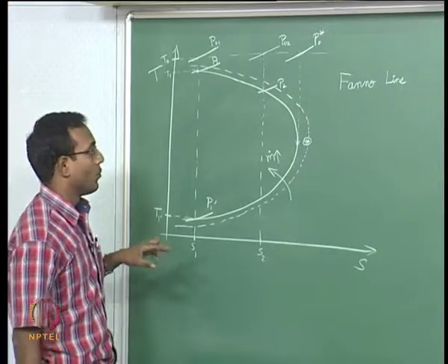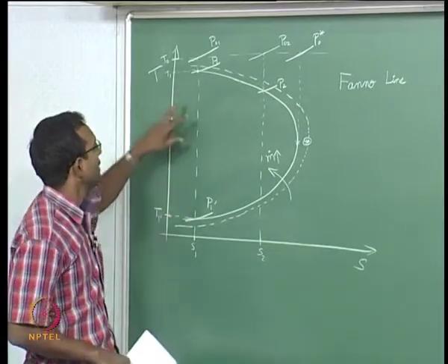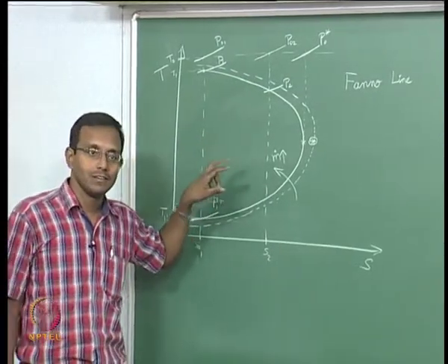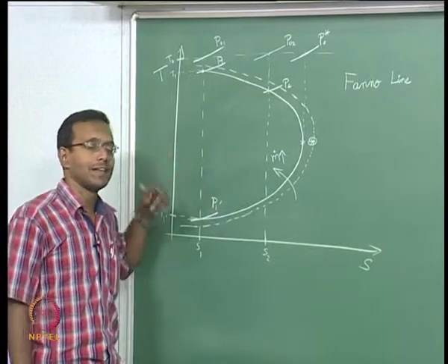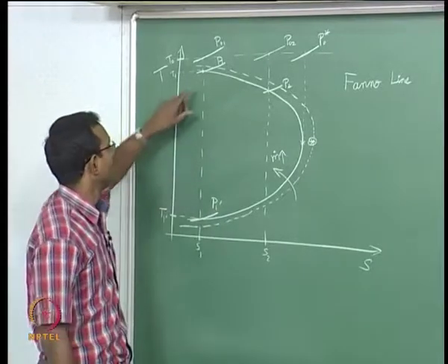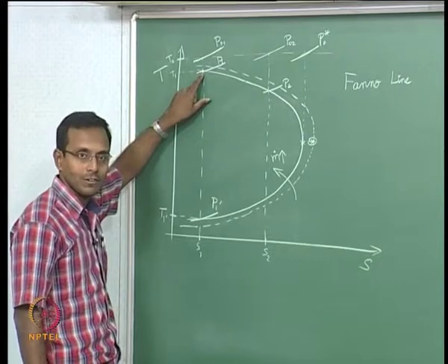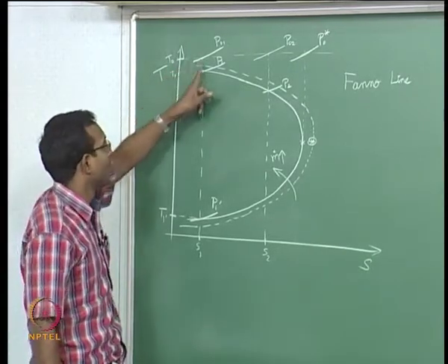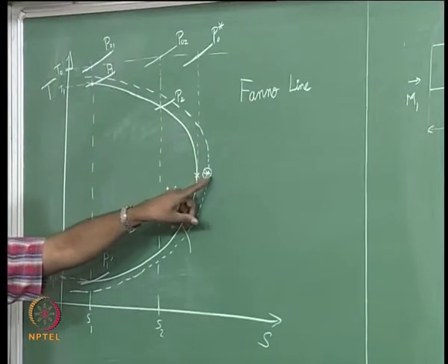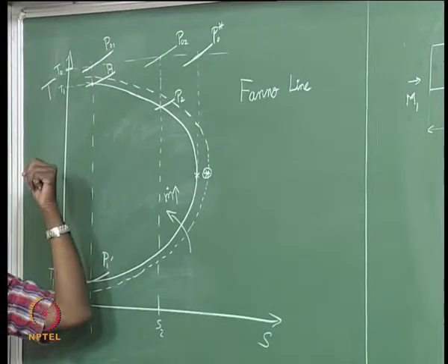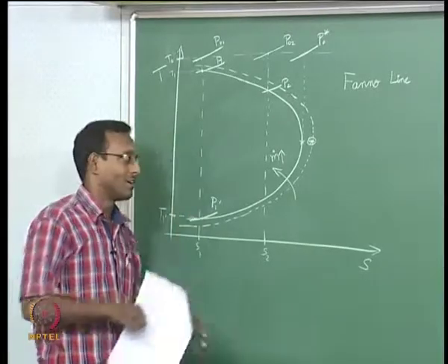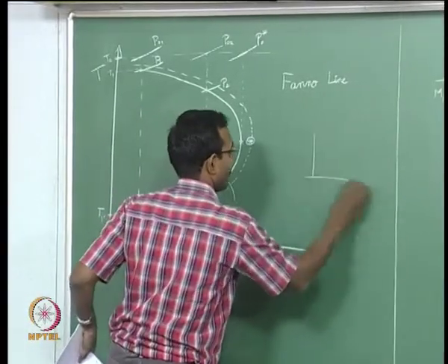So now what happens is, if I change my L star to be a little higher, length to be higher than the L star, then the solution jumps from this curve to the higher curve such that now it is all matched, and if I start from a lower Mach number, what happens to my L max subsonic solution? It will be higher. How do I know that? We just saw the plots, right? Plots were like this.